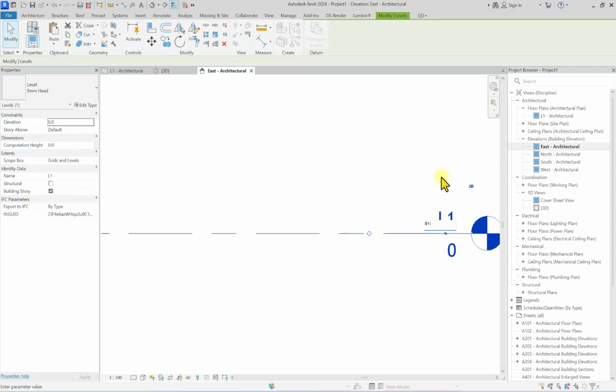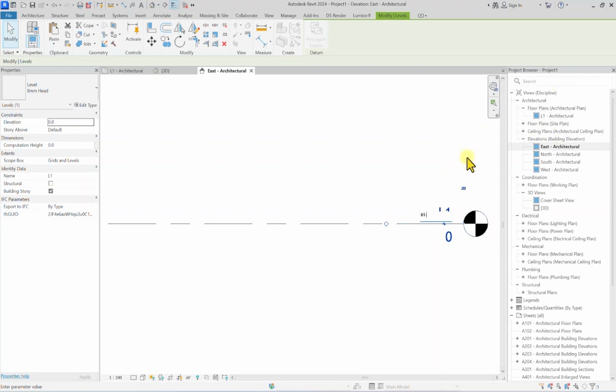The reason why I'm putting a numerical value is that when Revit is arranging floor plans, it follows alphabetical or numerical order. So if you just put the names of the levels without putting a number to it, for instance, NGL comes on the ground, then you have the first floor after NGL. But in terms of alphabet, F comes before N, so it's going to arrange the first floor first. So it's always important to put this numerical value, so it arranges according to the level height. So this is 01, and I'm just going to call this NGL.